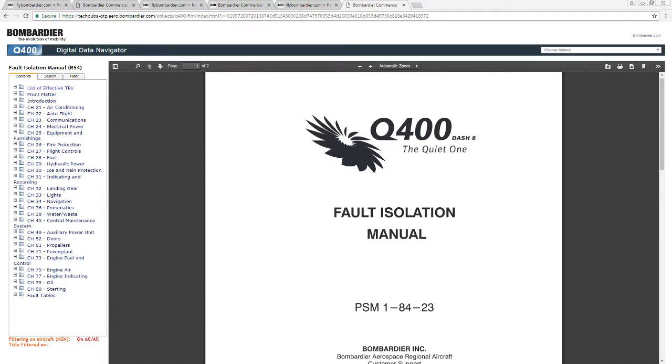What I'll be doing now with this video is taking you through the different documentation or manuals that will help you work through problems with EWIS. This video is a deeper dive into the troubleshooting procedures mentioned in the General Practices Phase 1 training. So we will be looking at 3 manuals in this video. We'll start off with the FIM, the Fault Isolation Manual, then the AMM, and finally the Wiring Manual.